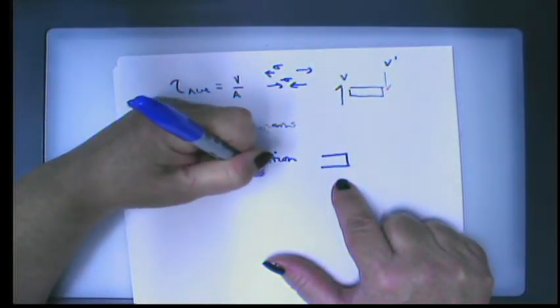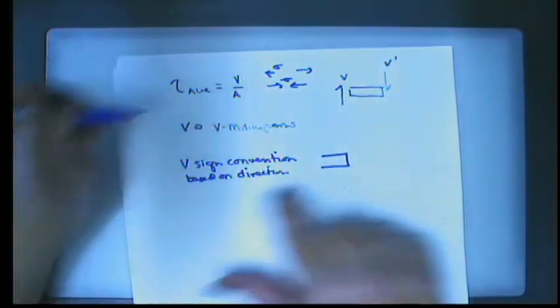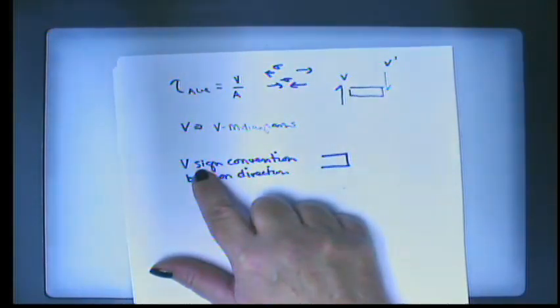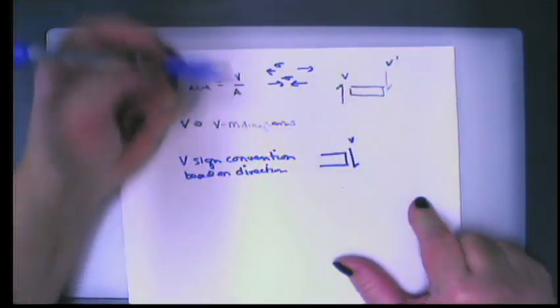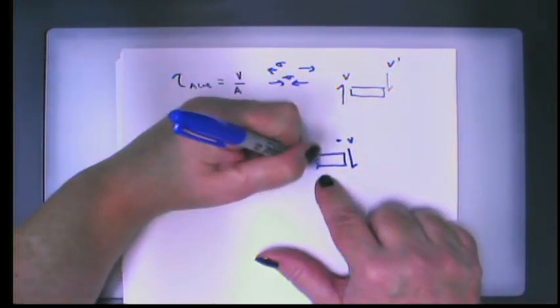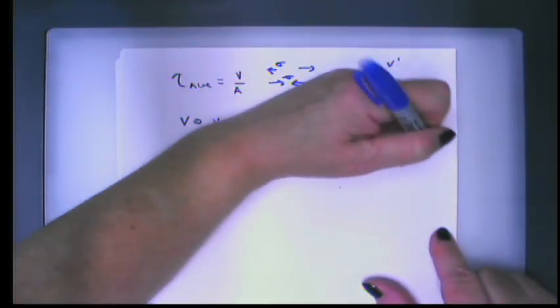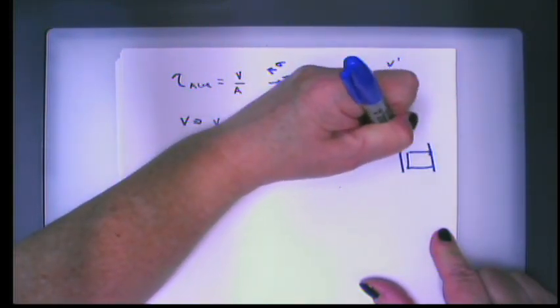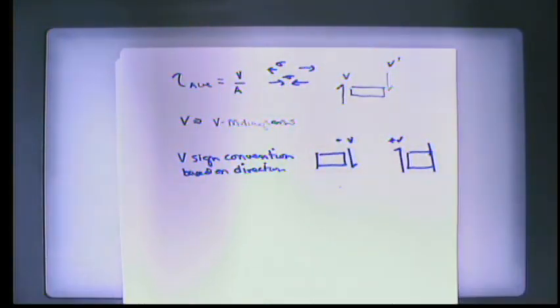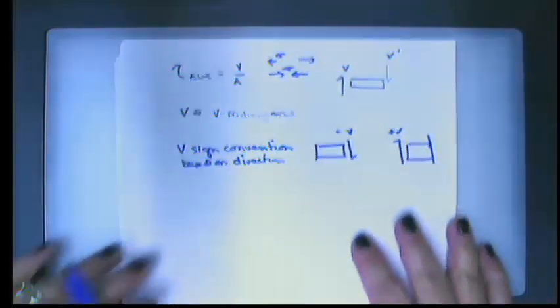And we need to know that because if we add shearing forces or shear, we need to know if we're adding or subtracting them arithmetically. But we've said that this is a positive V if we cut on the right, and this is a positive V if we cut on the left. So we just have an equal and opposite sign convention.